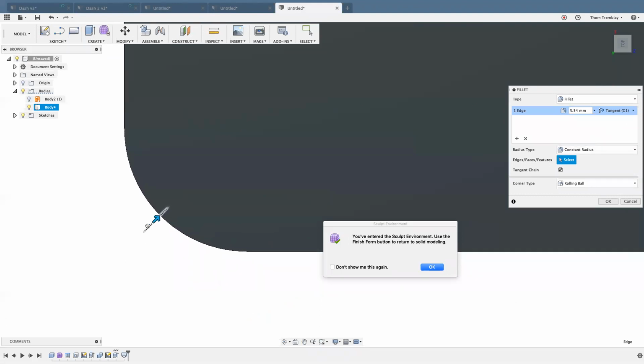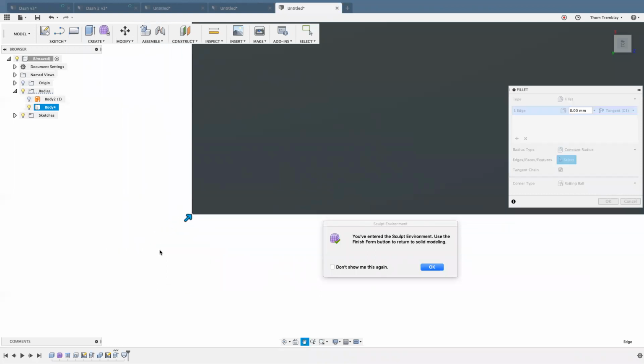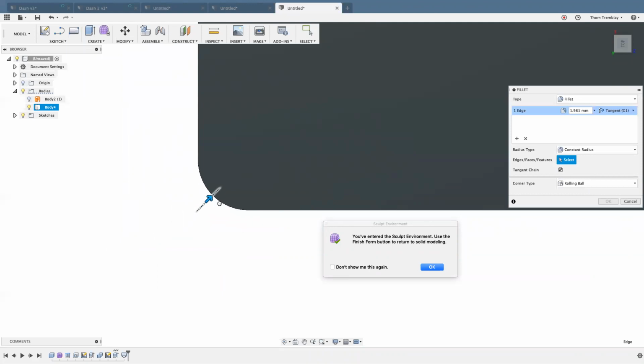So imagine G0 as that, a sharp edge between 2 faces looking at it from the side. G1 is just simply maintaining a radius that comes tangent to the faces on either side of it. G2 continuity takes the weight or the size of those faces and the angle of those faces that are adjacent to the curve that connects them and applies their weight. So it won't be a consistent radius all the way around that curve. Instead, the faces on either side, their angle, their size, will influence that curvature, that transition from one face to the other.